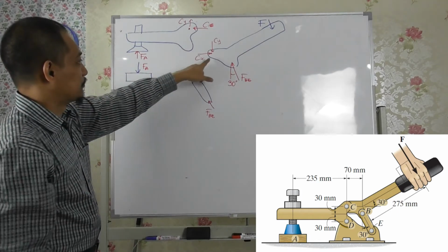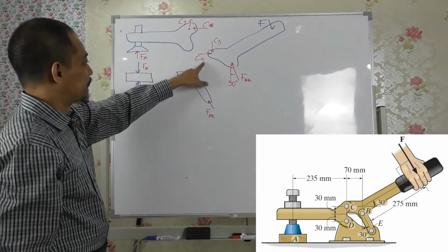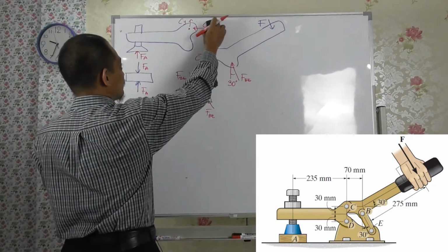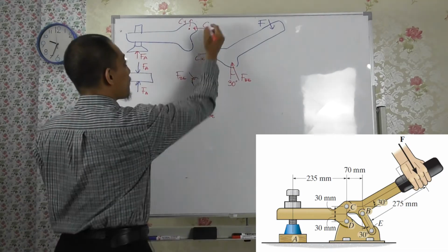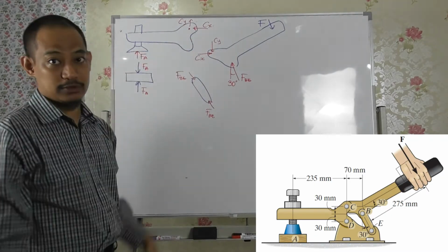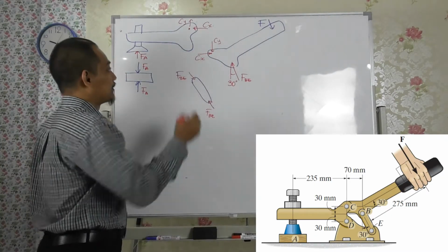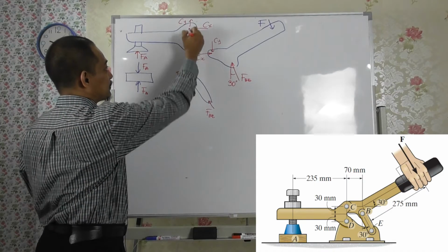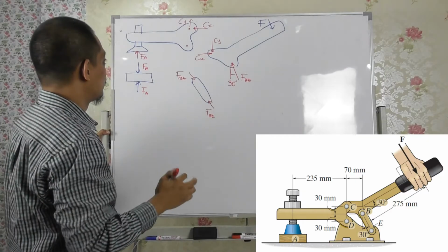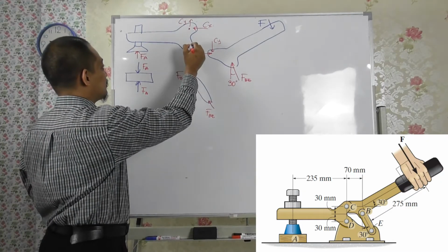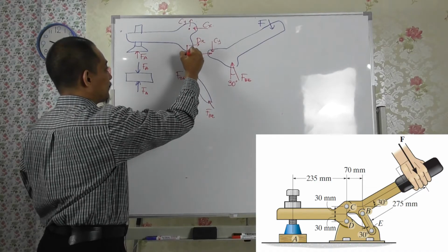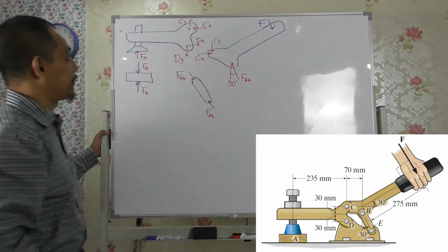Hopefully by now you have understood how we draw corresponding points, right? So for example, this point C, if CX is to the right, CX must be to the left here. This is X. And if CY is downwards, CY has to be upwards there. And then we have another point, which is point D, straight away under point C. Make sure all those lines are consistent. So here you'll just assume, let's say, DX like this and DY like that, right?